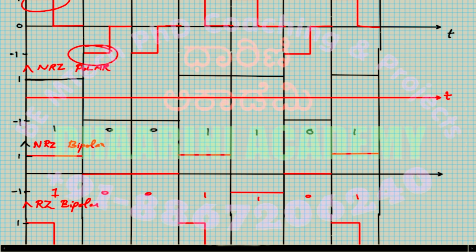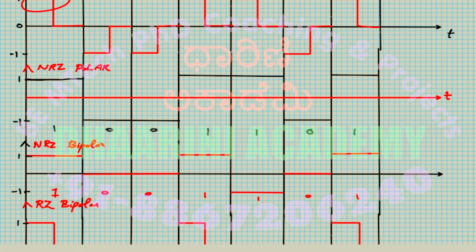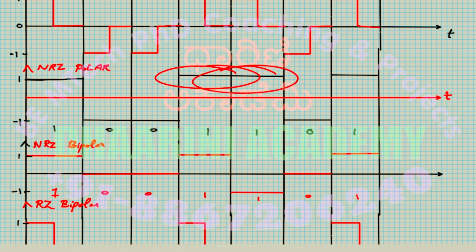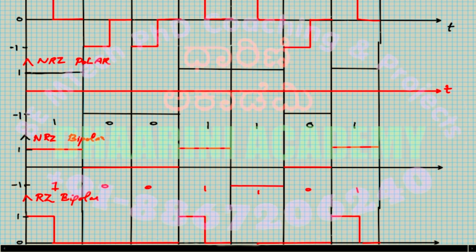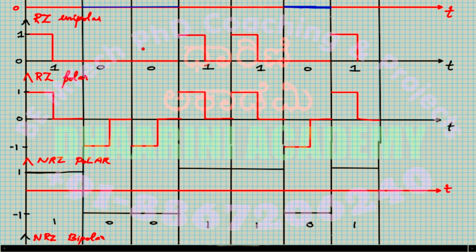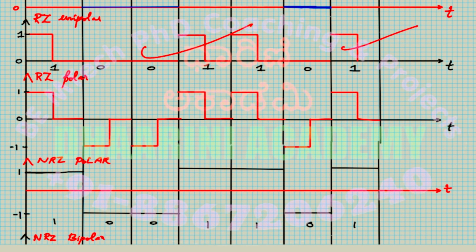Circuit is on means it is wasting power, correct? So you don't choose any waveform which makes your circuit on for the complete duration. Instead, choose something which is on only for half of the duration. Maybe this one. You see, it's half. Whenever it is zero, it is completely zero, when you are not sending anything. Whenever it is one, you are sending high for half the duration.